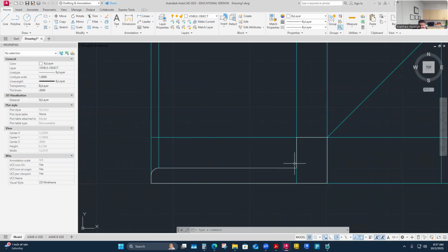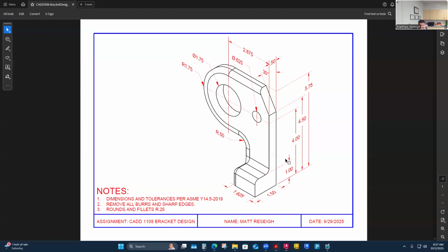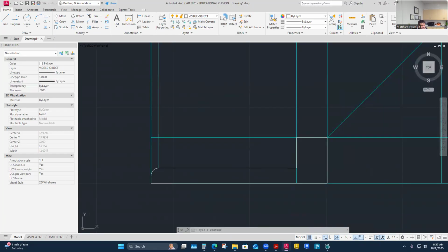It would be this fillet radius here from that surface up to the foot, this little radius. So I've got this surface coming up to this surface, and it would be radius, and then I would radius down into the top. So this little S radius here, which is a 1/4 inch. So I think I'll put this one in the front view, and then maybe just project it up, but it'll be about the same as offsetting the top view. And in the front view, I can do this radius as well. So let me do that.